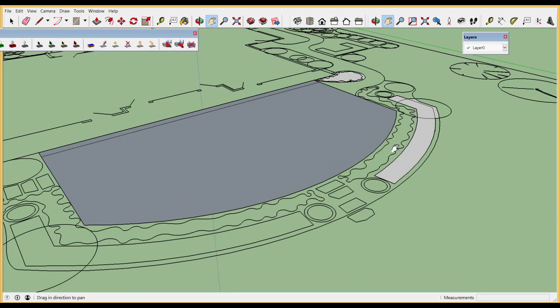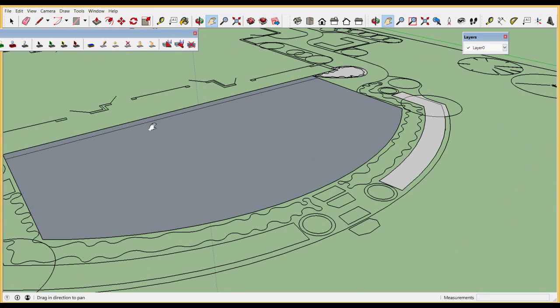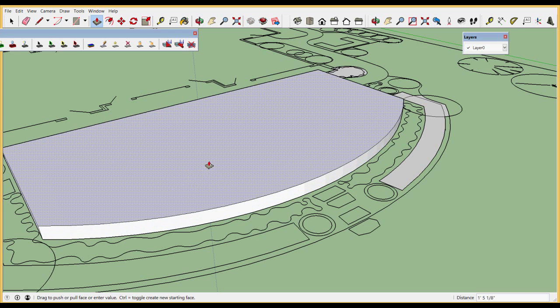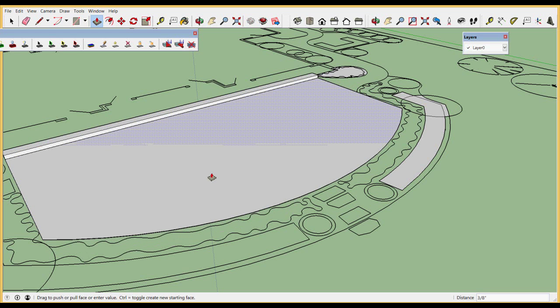So the surfaces that we created can be easily manipulated. It's just a matter of picking the push-pull tool, and we might want to increase the height of that step there. At the moment it's 7 3/4 of an inch. Let's imagine that it's 6 inches high. Let's leave this surface as is, although we could bring it up or down at will with the push-pull tool. But we'd be more interested in the hedge here.